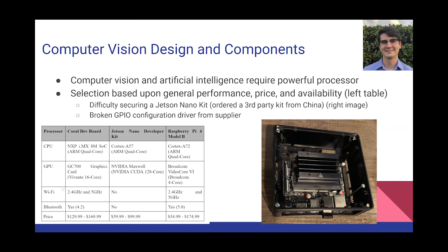One thing that we did not foresee prior to purchasing this was that the GPIO, which is the 40-pin header on the right side, if you can make that out, the configuration driver from NVIDIA does not work because this is a third-party board, and there currently is no solution to getting that driver to work between NVIDIA and Seeed Studio. So that has altered some design decisions as the project has progressed.